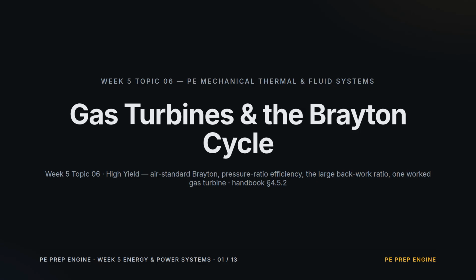Topic 6 of Week 5. Gas turbines and the Brayton cycle. 4 processes: compress, burn, expand, exhaust. We turn one pressure ratio into a thermal efficiency, then meet the trap that separates gas turbines from steam plants, a compressor that eats most of the turbine's work.